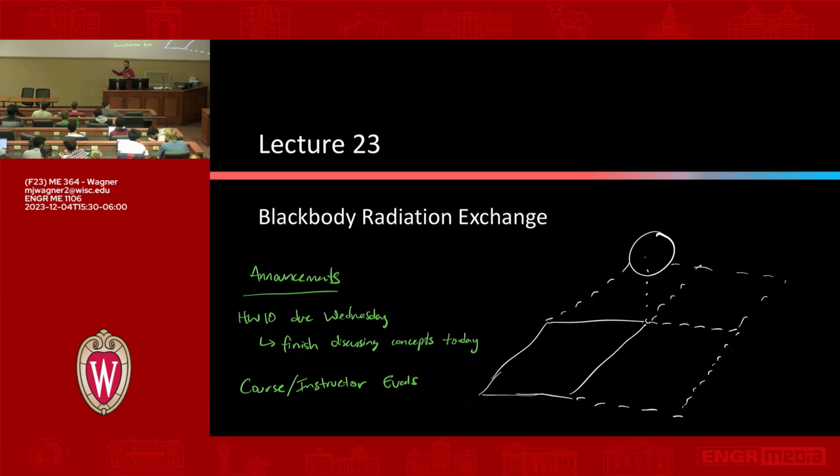From the sphere to the bigger surface, remember you can use virtual surfaces. You can do the same thing. You can use the idea of adding things together. So for a view factor to this, you could take a slice out of this view factor here and subtract that off, and that would be the view factor to the bigger surface. So you don't have to have a library for everything. You can take advantage of symmetry, reciprocity. You can take advantage of adding things, subtracting things. Just keep in mind the overall energy balance idea, that the energy that you're accounting for has to go somewhere, and it's going to add up.